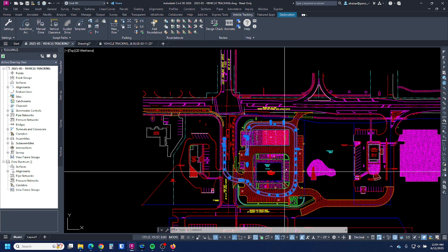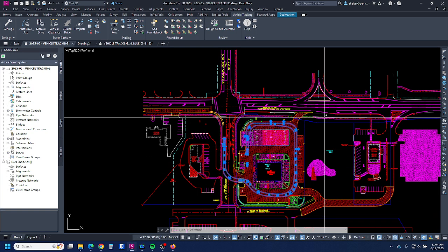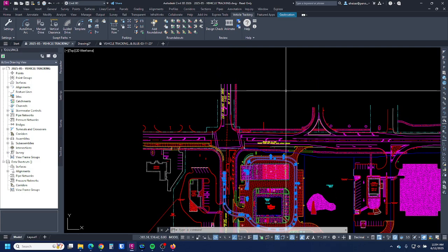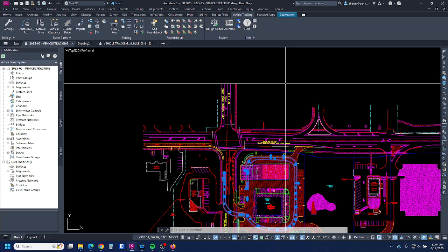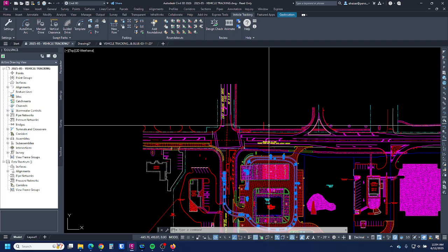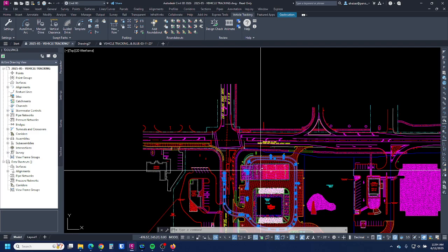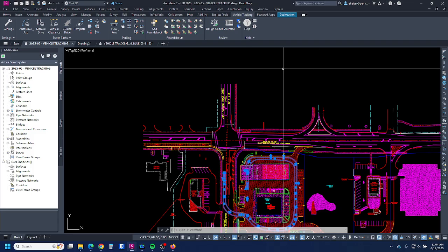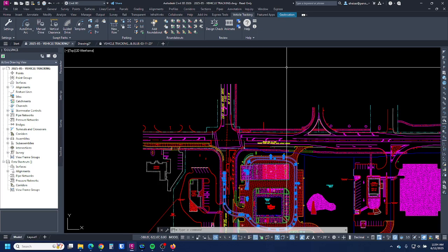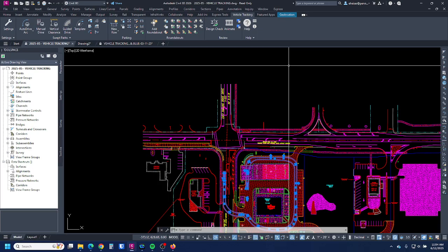So sometimes, if I have a drawing that has several turning movements, I will just put a dummy movement near wherever I want my profile to be and tie the profile to that. That way, if I purposefully delete one of the movements on the site, I won't accidentally be deleting my profile. That's just a tip, because it's bit me before.